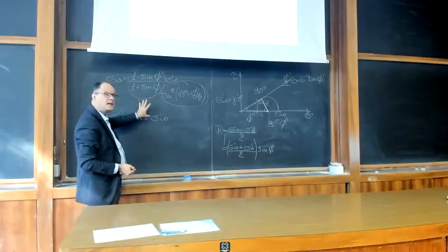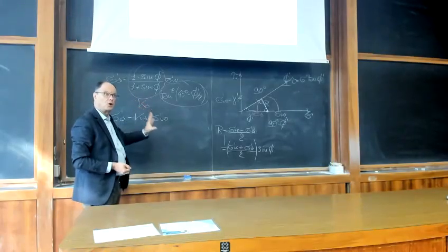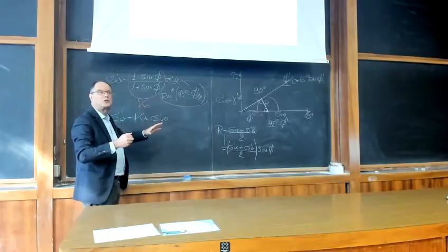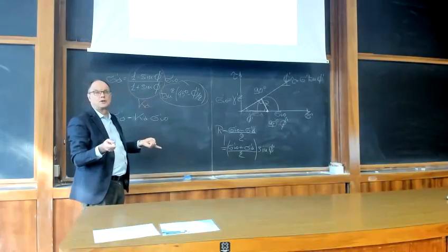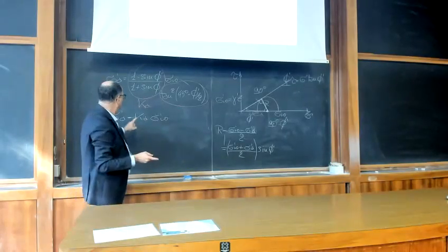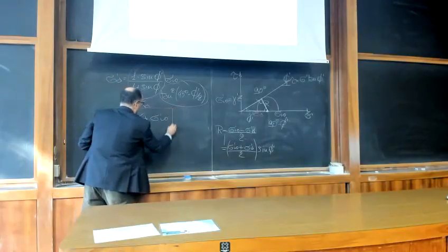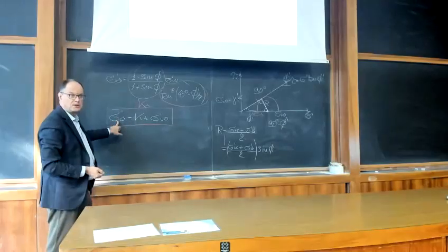So Ka is the minimum earth pressure coefficient that you can think of. You cannot go lower because the soil fails, so you can no longer reduce your Mohr circle. Now you have this expression, and you can know sigma A.